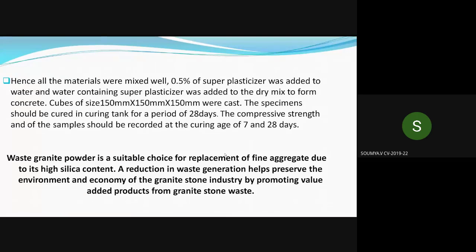Granite powder generally contains high silica and is suitable to replace fine aggregate in concrete. Using this granite powder reduces waste generation, which helps to preserve the environment and the economy. This is because granite powder is available in large quantity at the quarry sites. So next slide, please.